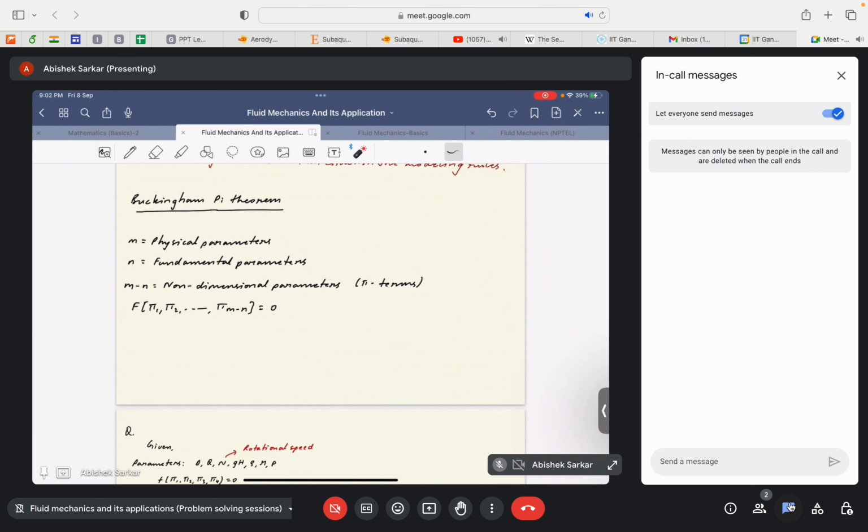So you need to deal with these non-dimensional numbers, and after doing the experiment or tweaking these non-dimensional parameters, you will know which parameter is actually affecting the flow the most, that is actually driving the flow, and which non-dimensional parameter is affecting it the least, which essentially can be neglected because it does not have an integral role in defining the flow field.